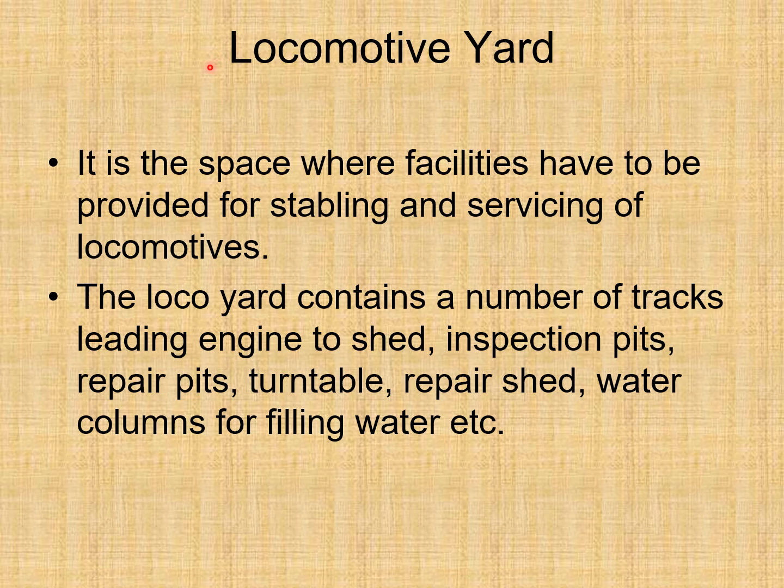Then comes the locomotive yard. It is the space where facilities have to be provided for the stabling and servicing of locomotives. The loco yard contains a number of tracks leading engine to shed, inspection pits, repair pits, turntable, repair shed, water columns for filling water, etc.